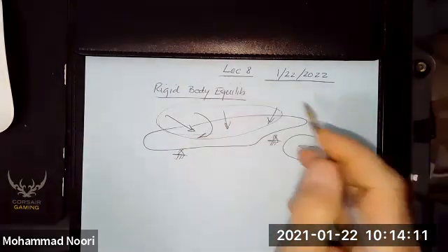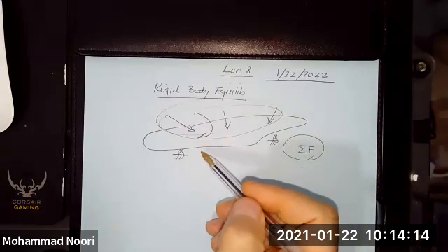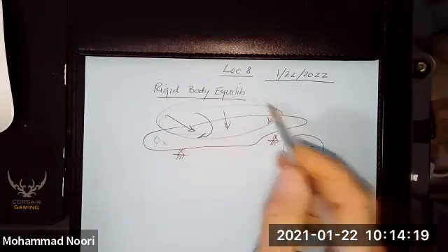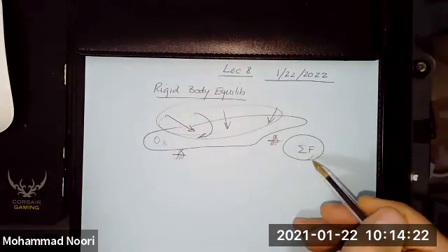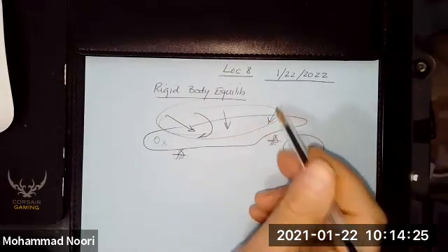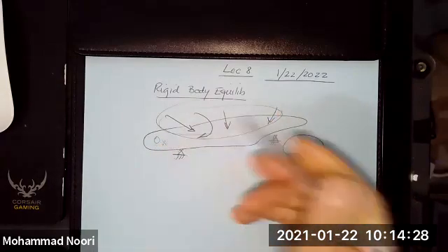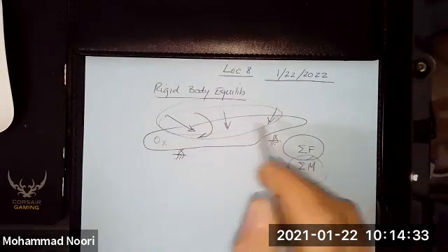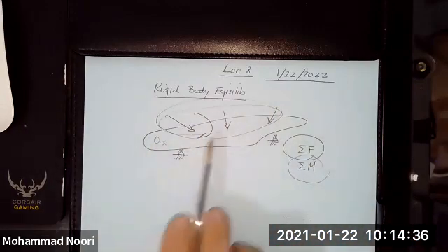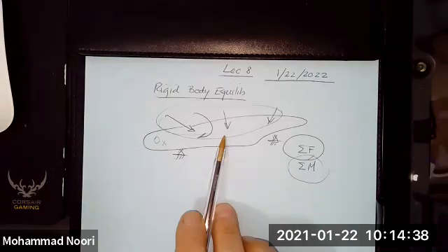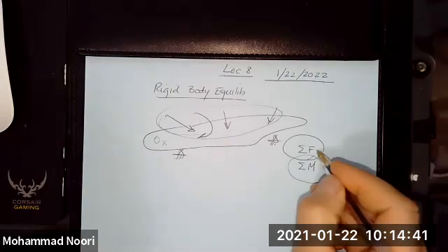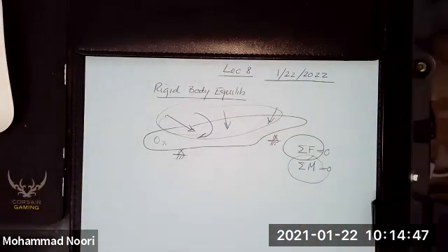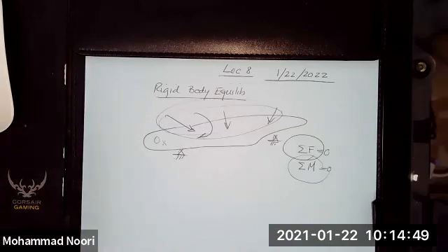So we learned that all of these forces can be replaced by just a single force that is a resultant of all the forces acting on the object. If you move all those forces to a single point, you can replace all of these by their resultant. And by performing that action, you end up with also several moments that you need to add to that point. And since this object is not moving, is in equilibrium, these have to be zero. This is the premise of static equilibrium.